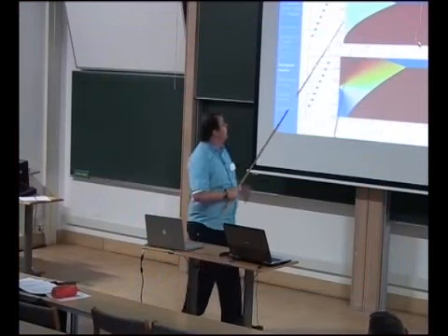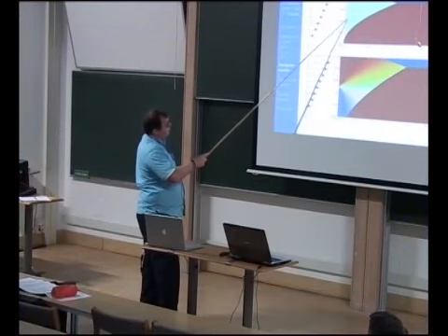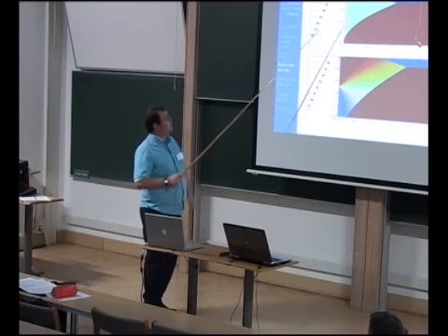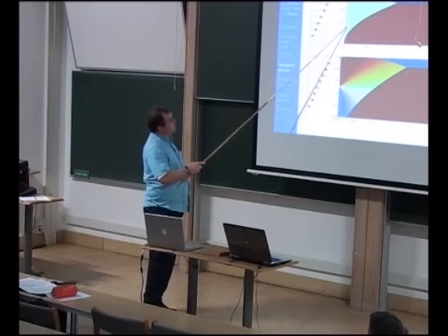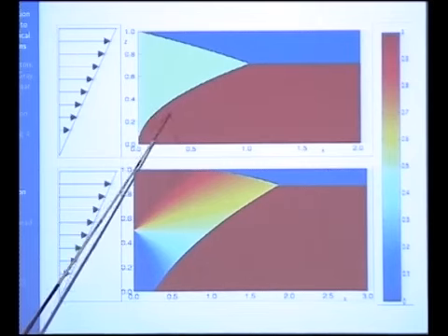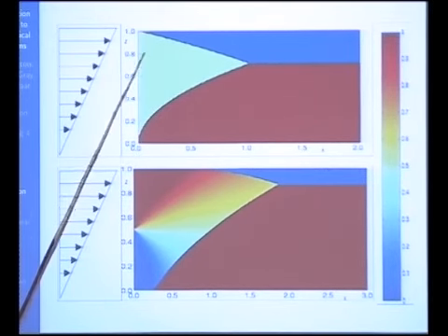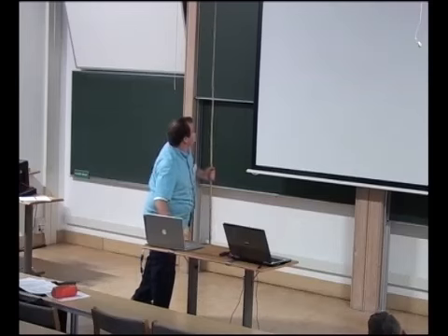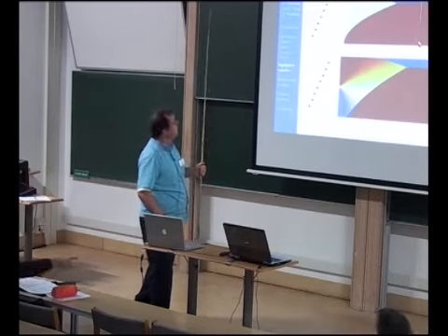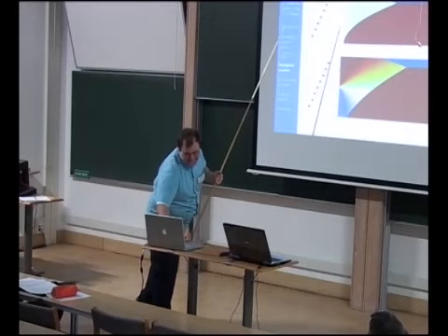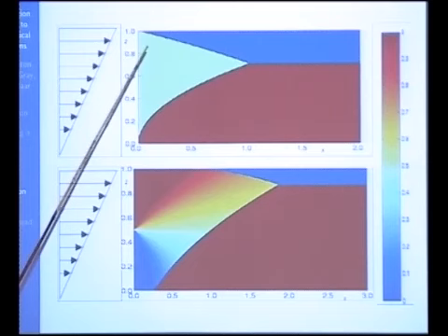What's actually going on in these problems, if you consider a small particle coming in here, is that the small particle percolates down past the large material, leaving it up. So the process is, the small material percolates down, leaving the large material up, and eventually it has percolated down and pushed all the large material out of the way. So it enters a region of pure small particles where it's perfectly happy and carries on. And similarly, you can figure this line here as there's a small particle just there and it starts to percolate down straight away.